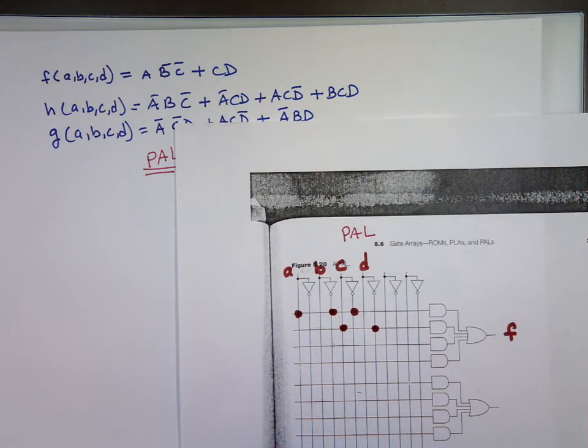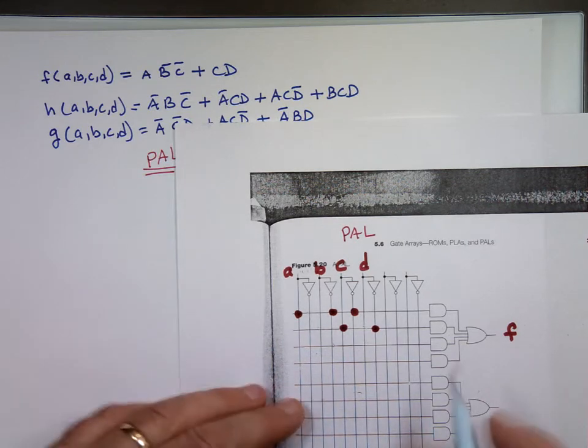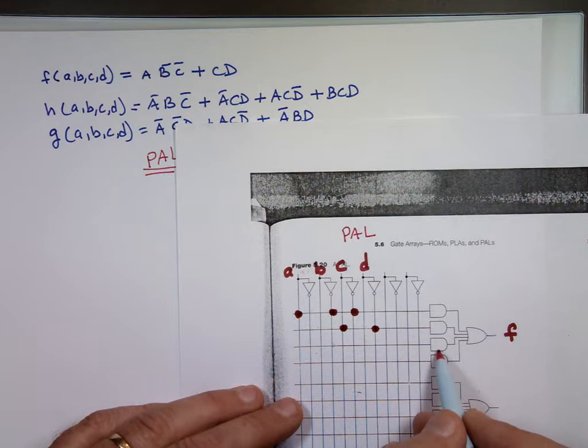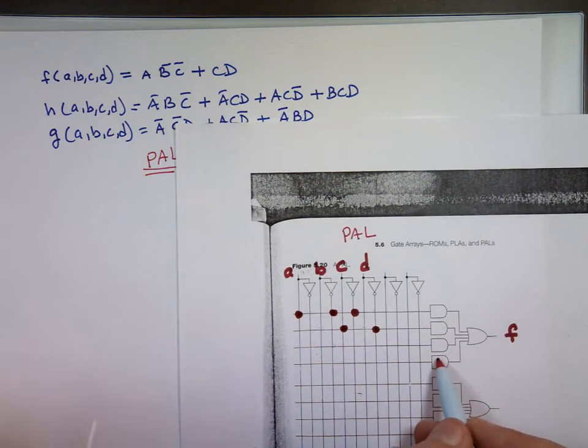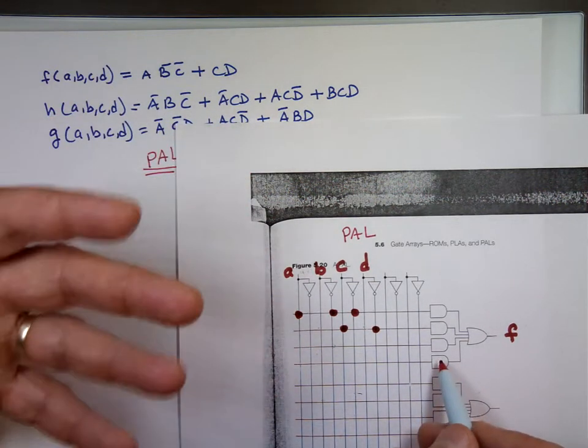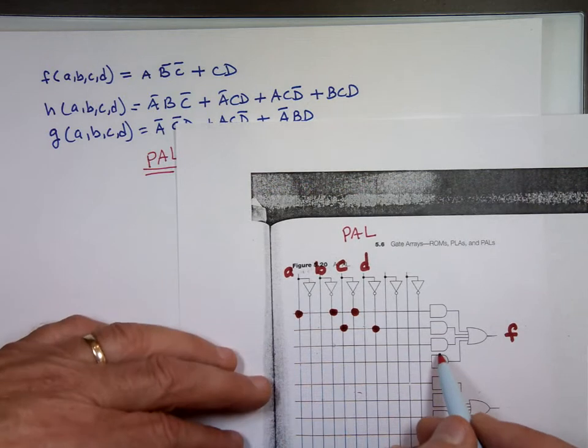So to make sure I don't get bad noise, bad signal, what I might want to do is kill these 2 gates to make sure I never get anything crazy from them. And if you want to kill them, for safety, what do you attach to it?